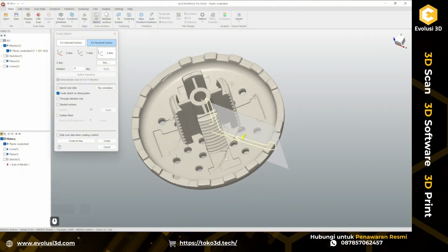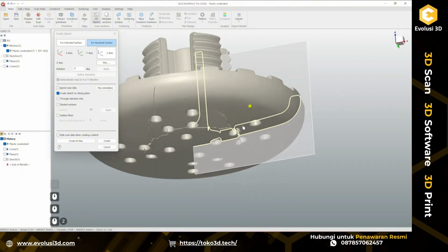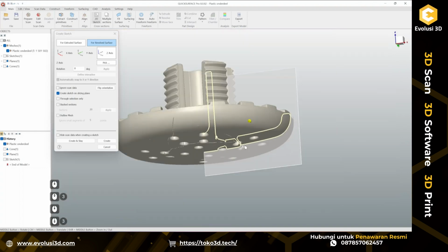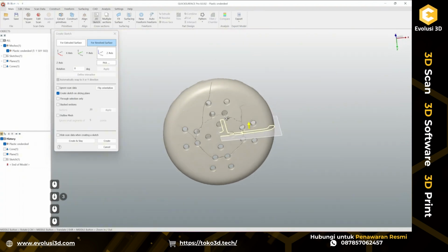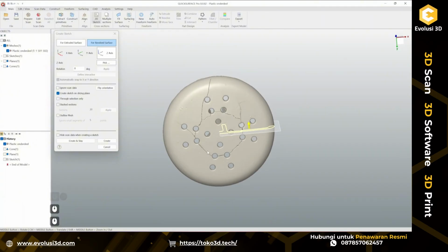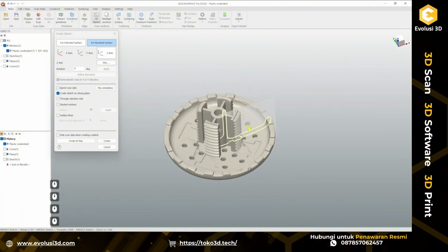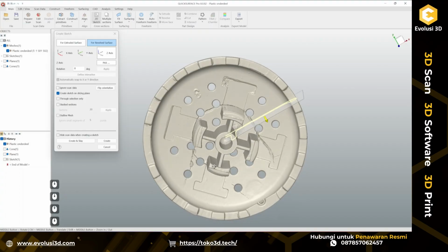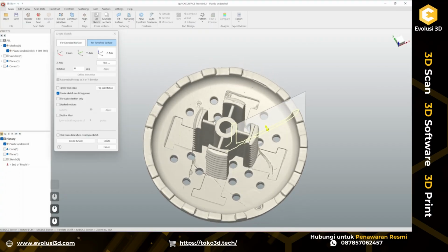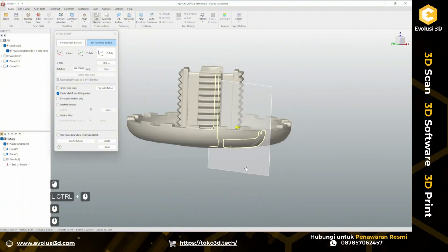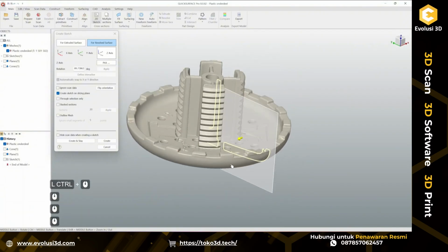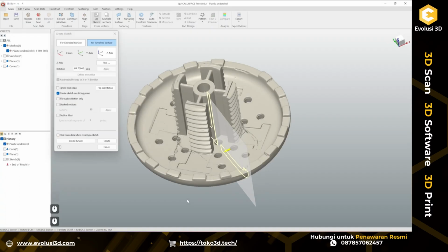So on this side I can see I have this crack here and some slight misalignment of surfaces, so I want to try to use a different zone of this part where I have less deviation between surfaces, and probably I could use it here. Just set this to exactly 90 degrees and hit create.